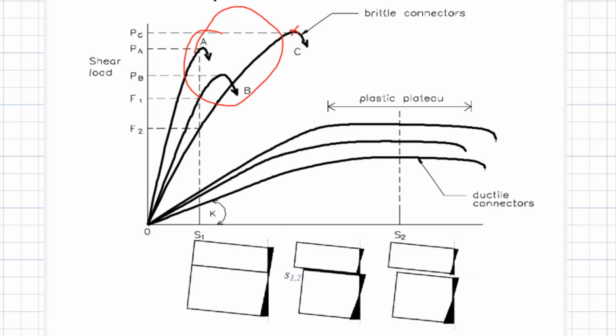So this failure is very similar to my rigid connector behavior, right? Rigid connectors will fail suddenly. They will separate off at the interface. I'm not saying that they're going to fail early, they have more strength. As the load increases, when they reach the ultimate stress, they will just separate.